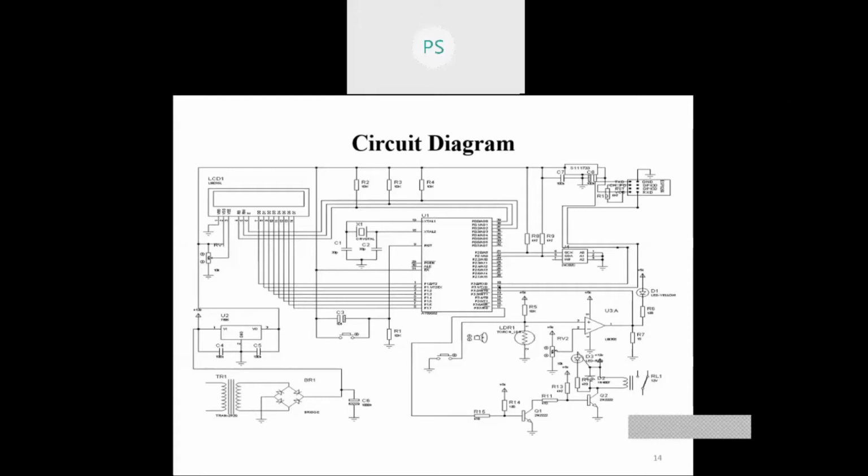According to the datasheet, the 89S52 can operate up to 33 MHz, but we are using 11.0592 MHz as the microcontroller will communicate with the Wi-Fi modem through serial communication. In case of serial communication, we have to use 11.0592 MHz for error-free data transfer and reception.